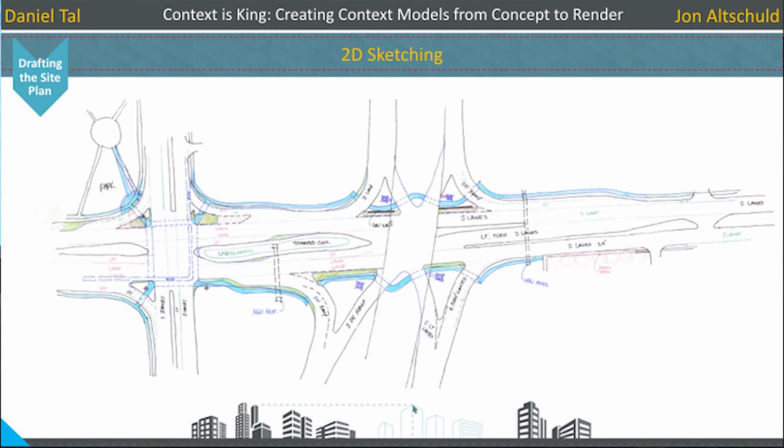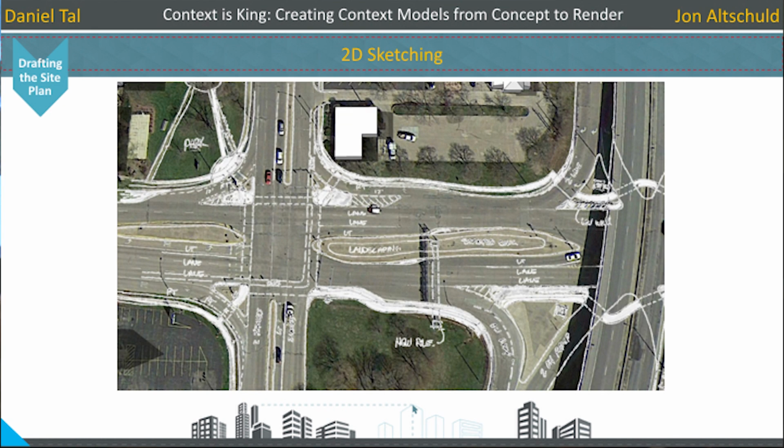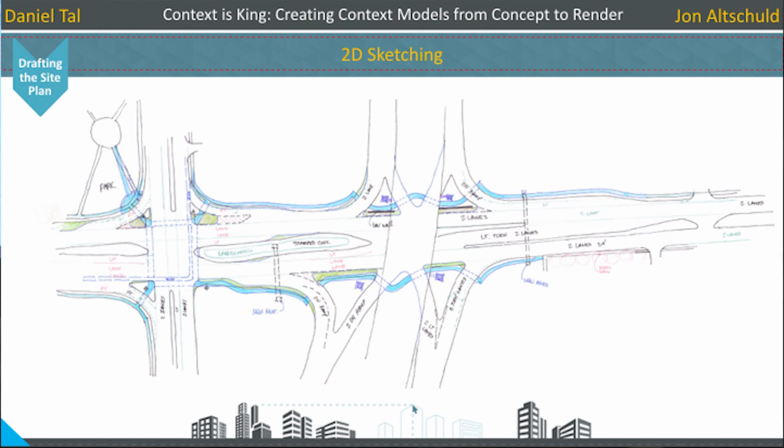So we take this PDF of information, and then what we do with it is, using the same process, swap out the low resolution aerials with the high resolution aerials in Photoshop. We take the PDF, make it a PNG, overlay it onto the aerial, and then we bring it into SketchUp. It's not always the best interpretation of that information, versus the refined line work that you see here, or relatively refined line work.